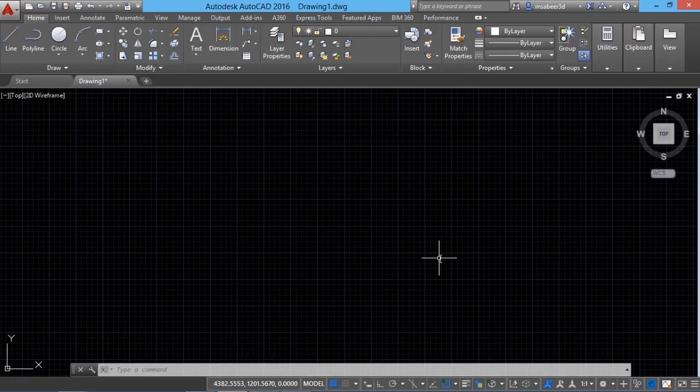In this video, I'll introduce you to points, circles and arcs in detail, and we will see the various methods to construct these objects in AutoCAD. We will start with a point. A point in AutoCAD is a node which will act as a place marker to construct so many other objects. A point has got absolutely no size and it can be constructed using a variety of options.